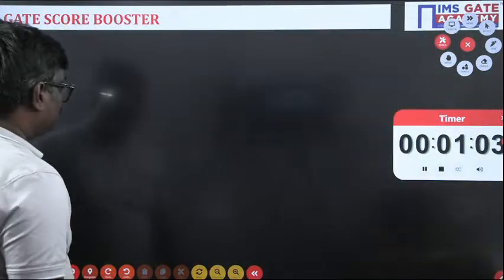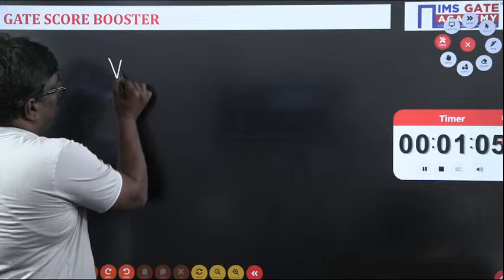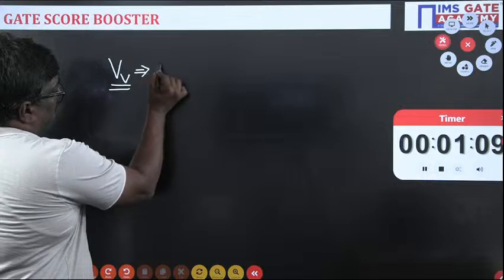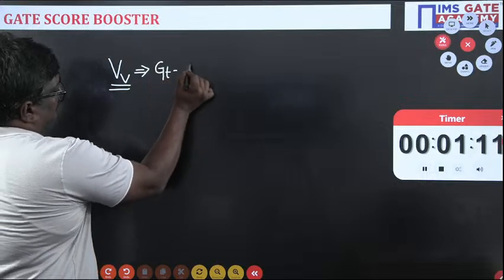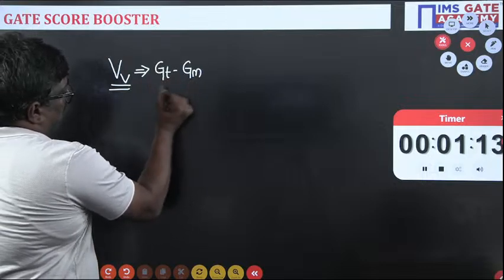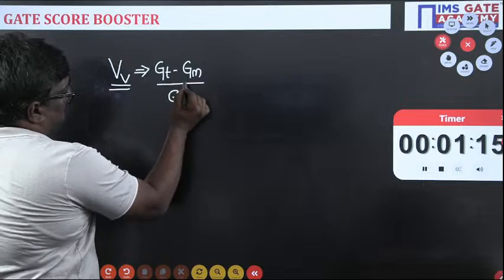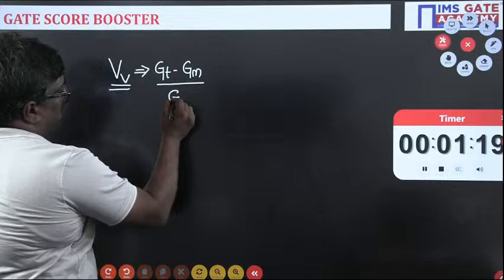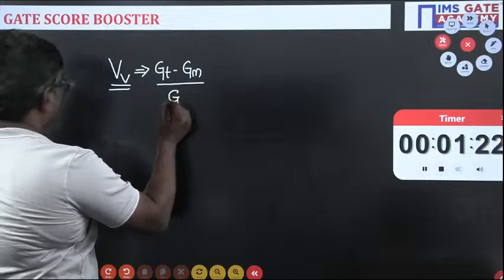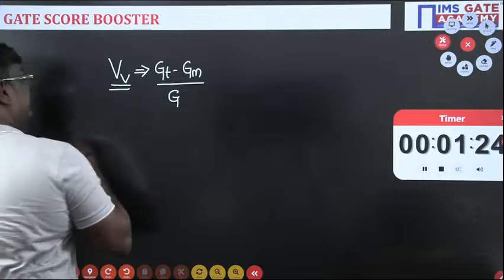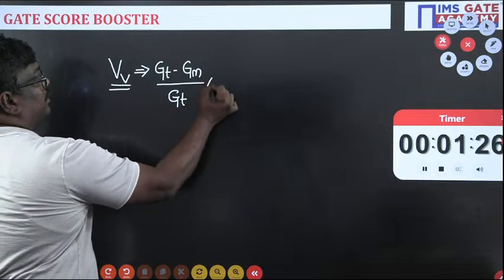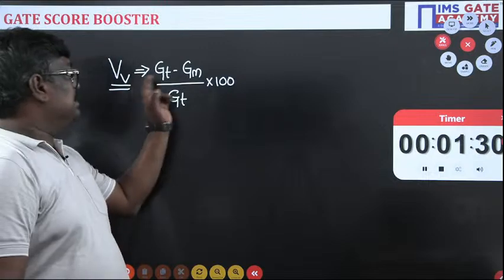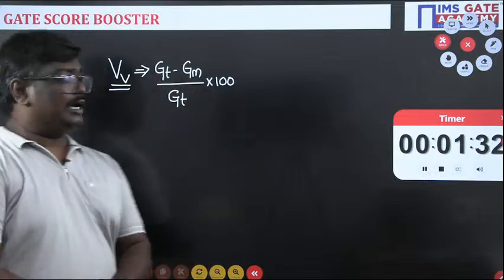Now see students, first of all let me tell you, volume of voids is given by the formula GT minus GM by GT into 100. Here, what is volume of voids, sir? GT minus GM by GT into 100.